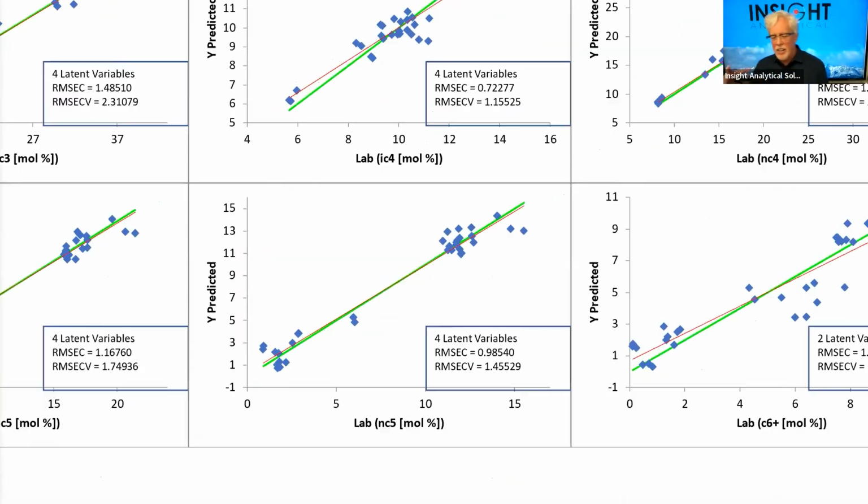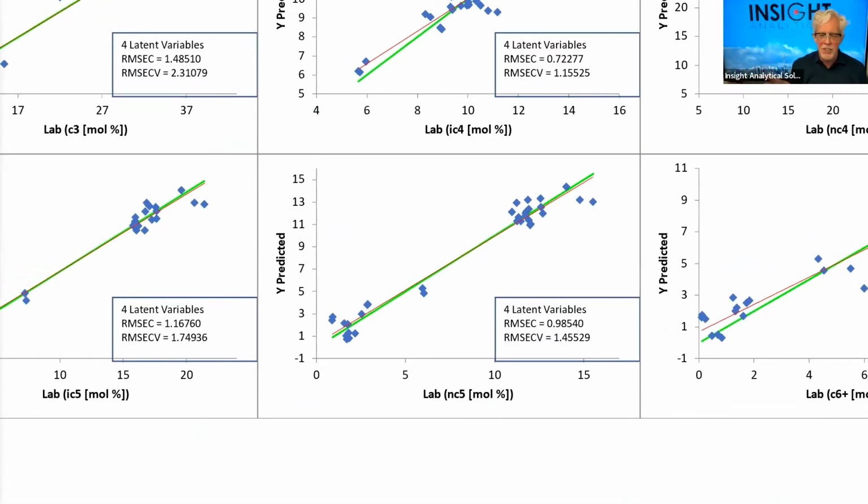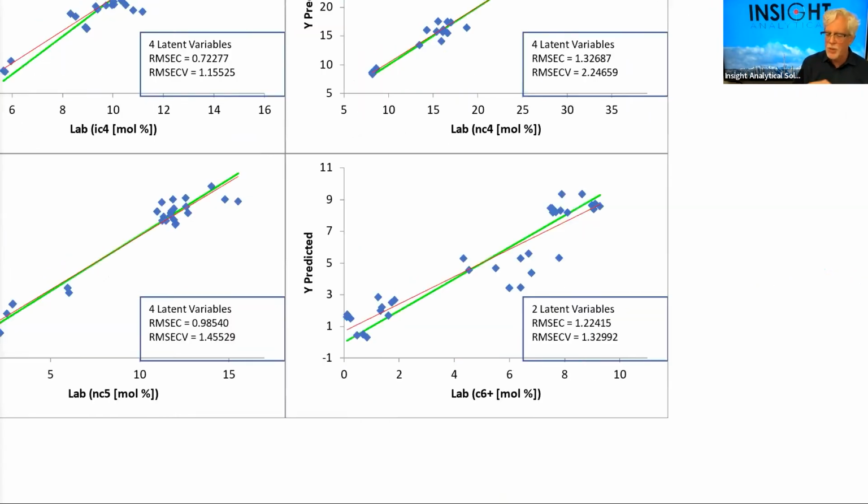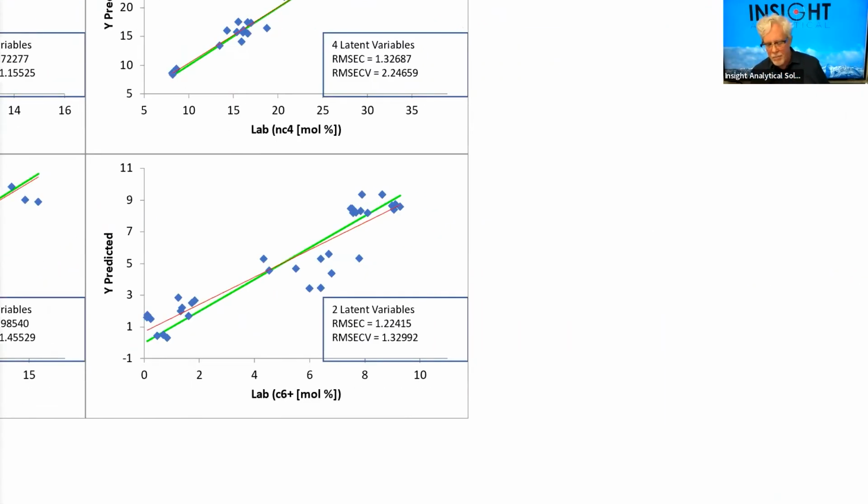And my point here is that this analyzer in real time is providing us chemical composition of each of these individual components and BTU numbers with no moving parts and no little injection valves. So I'm going to show this going right out to a C6 plus analysis.